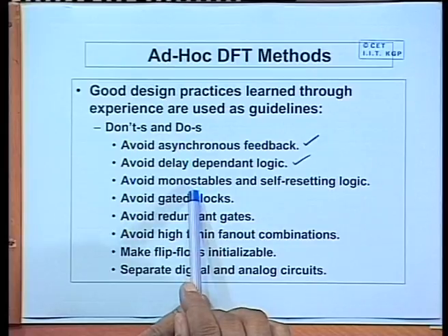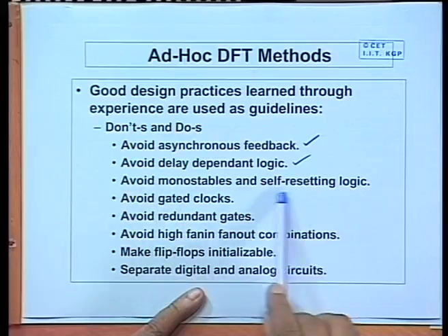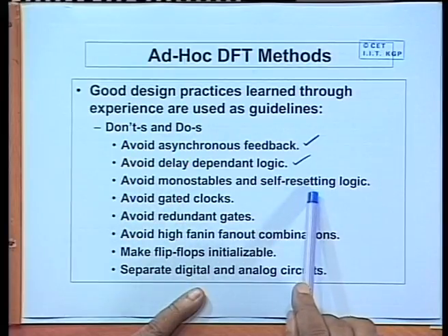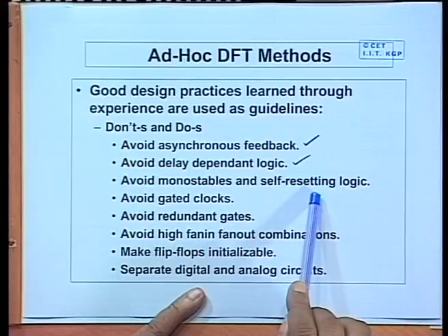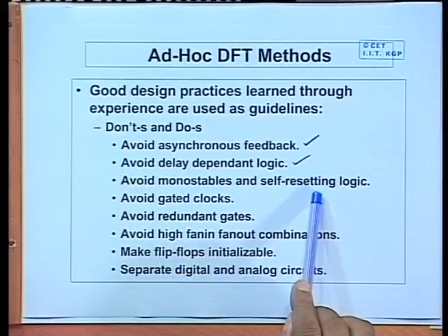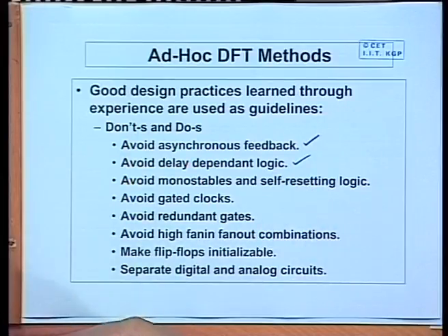Monostable multivibrators and logic which can reset itself to a known state are not recommended. The designer says that if you have to reset some logic or some counter or some register to a known state, there should be a reset signal which can be given from outside. Externally you should be able to reset the circuit, not using some logic inside which automatically resets itself, because if there is some problem in the reset logic, it will be very difficult for you to test.